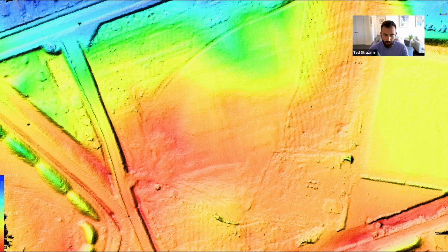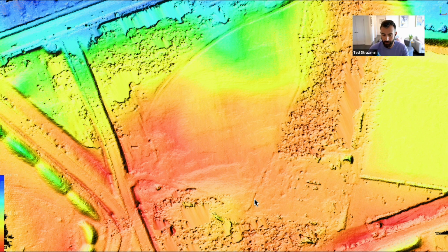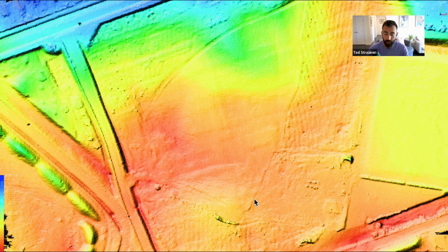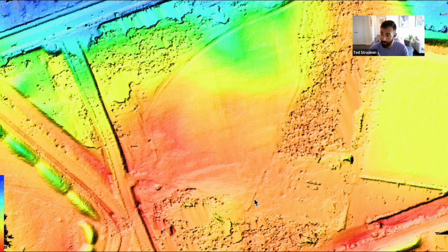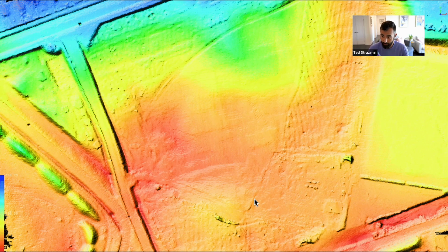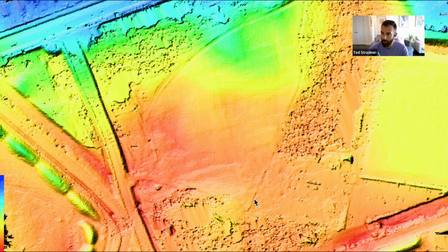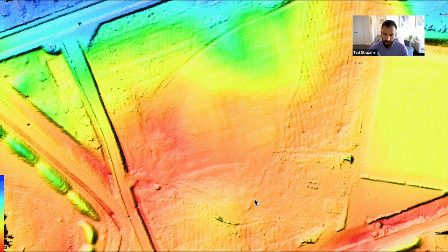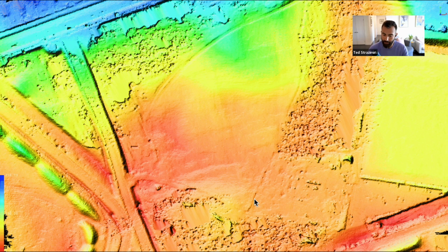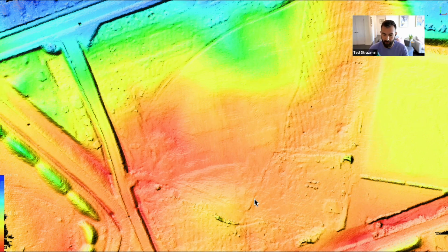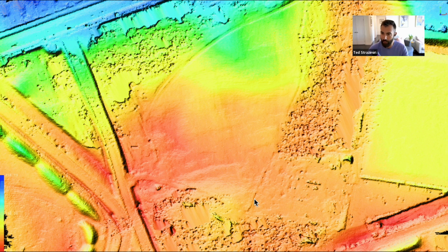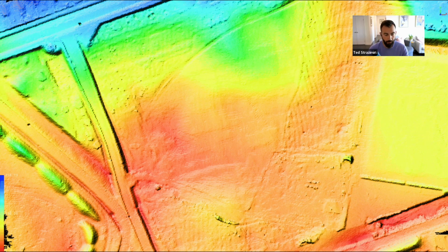And so the first result, right, the most common would be this digital terrain model that I have here. And I'm actually flipping here between the digital terrain model, the DTM, from the LiDAR dataset and the photogrammetry dataset. So I think you'll notice where they change, right? It's in those areas that had all of that vegetation that you'll see these gaps and these holes essentially in the RGB dataset. Whereas the LiDAR dataset has a very nice and even continuous contour.